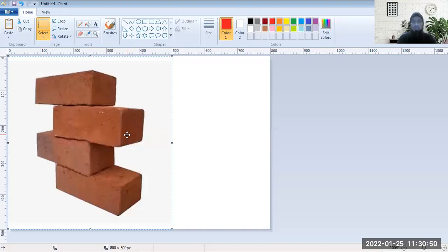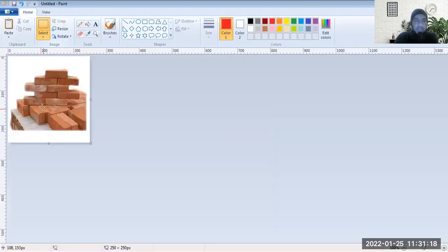And when two bricks are struck with each other, what happens? They give us a sound of a metal, like tang. That's the sound that you get once the Class A bricks are struck with each other. So then you have Class B bricks, which is worse in quality, somewhat like this. They will not have proper edges. They will have some bends somewhere in them, so they will not be a proper shape.